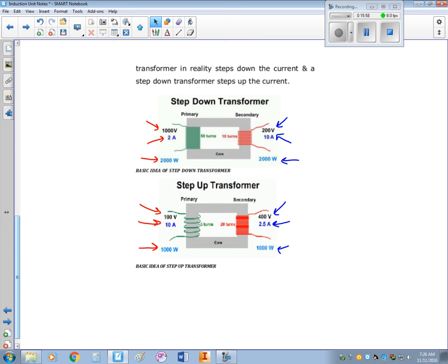High voltage power lines transport electricity at like 100,000 volts. I mean, it's really high voltage, but it's really low current. So when that really high voltage encounters the transformer outside of your home, that transformer steps the voltage down to 110 volts. Well, it's closer to like 220, but it steps it down to something that's usable for your house, but it also increases the amount of amperage available.